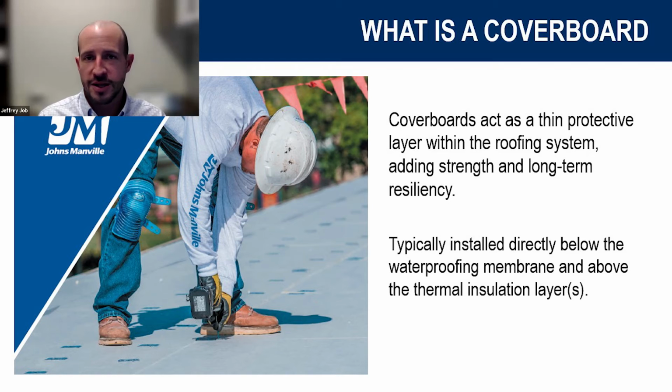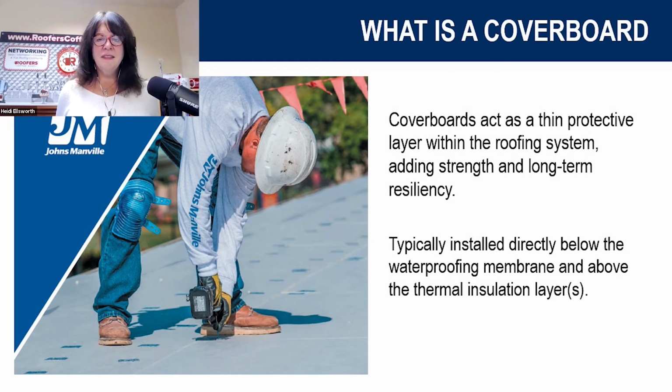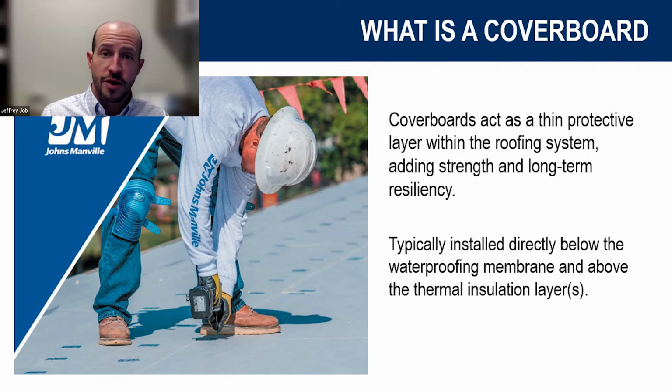From a low slope standpoint, the two biggest cost components of a roof system are going to be the insulation and the membrane. So the addition of a coverboard can go a long way in helping protect both of those high cost components of a system. So that's the beauty of the coverboard. Lots of different coverboard options out there.